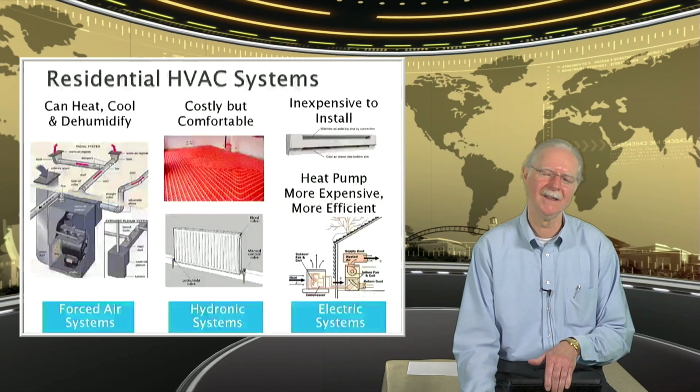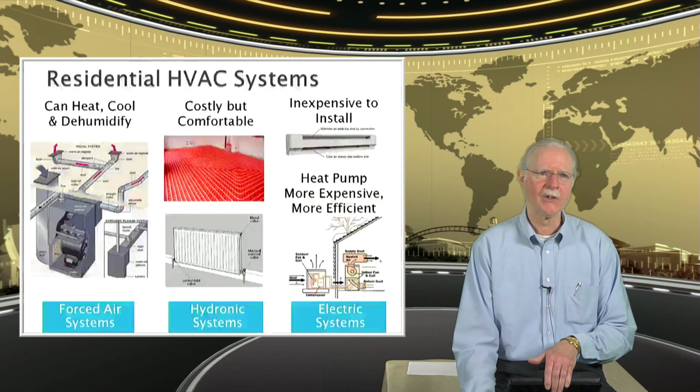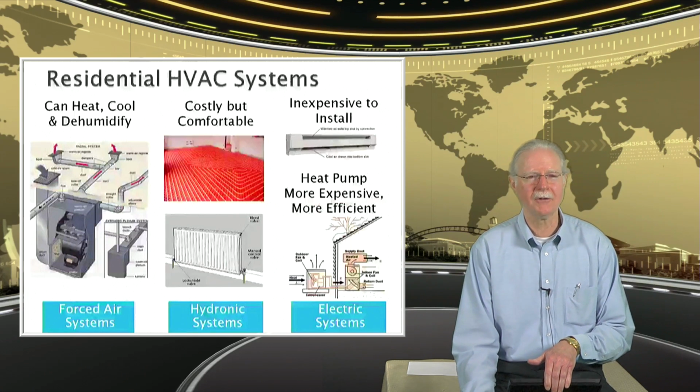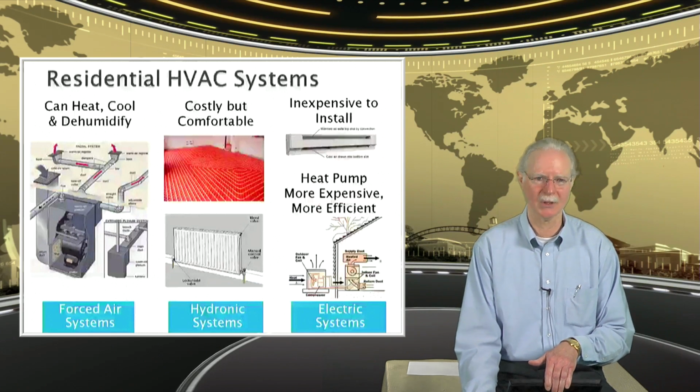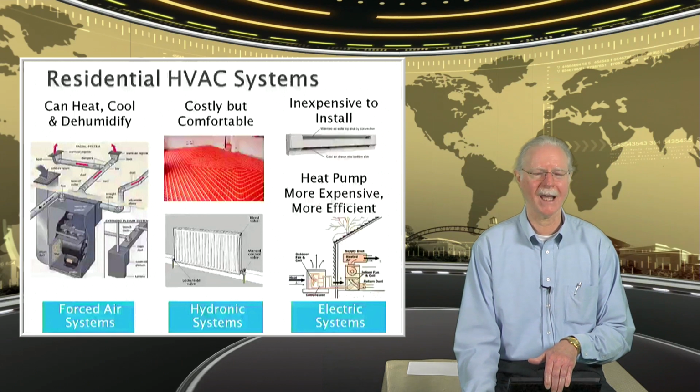Is there any chance of leakage in the hydronic system, especially when you put them in the slab? So the question of leakage in the hydronic system is an appropriate one. Does a leak ever occur? Absolutely. Does it occur less often now than it used to? Yes. And there's a couple of reasons why that's the case. One of them is, you really can't tell too much in this picture because it's rather small, but in essence, all of those pipes are one continuous pipe.